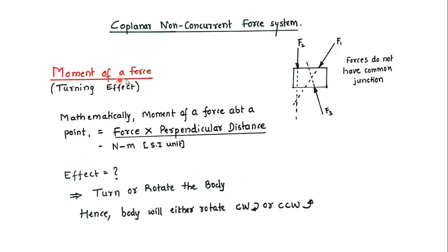Now what is actually moment of force? It is turning effect. See, this is easy to digest, this word turning effect. Okay, so that is nothing but moment of a force. So mathematically we write it as force into perpendicular distance. This is how we evaluate moment. The SI unit is Newton meter.